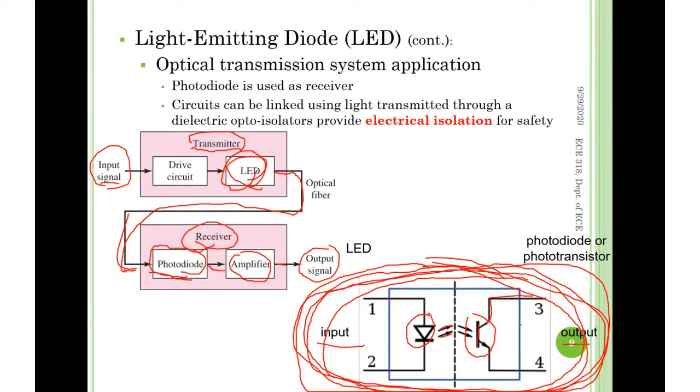Isolate two areas of different power rating, especially on what? PCB board. Okay, PCB. So isolation. Very good. This is something that's a must. It's not like we just figure out another way to transmit the signal. No, it's something that must be done, for safety.